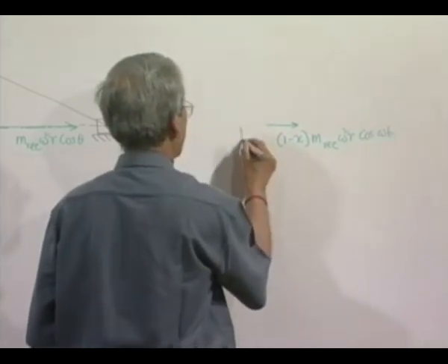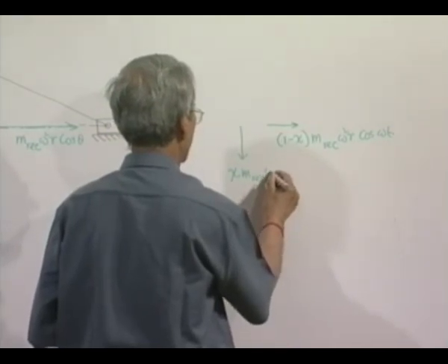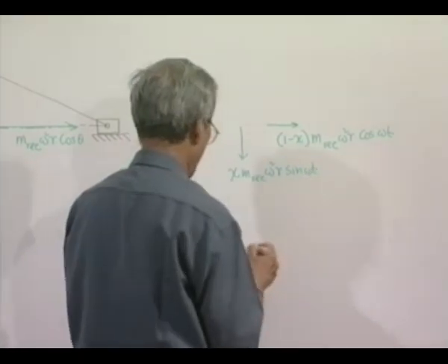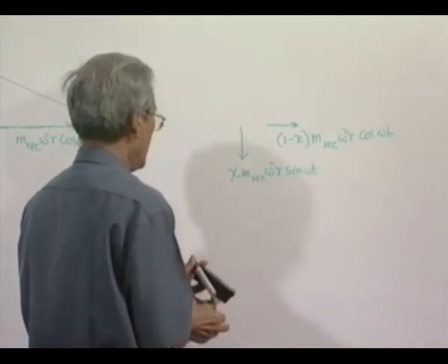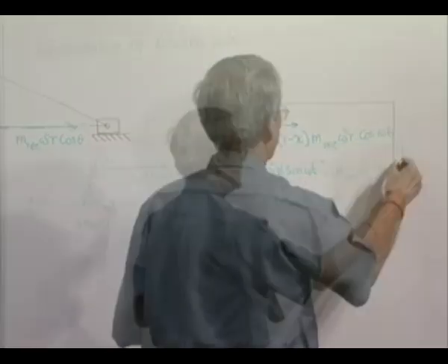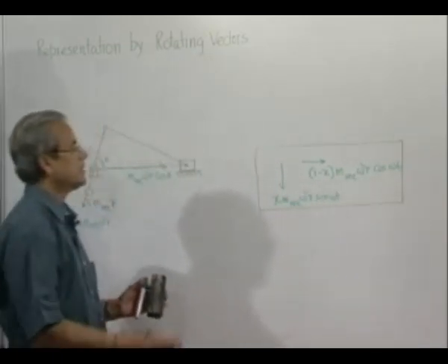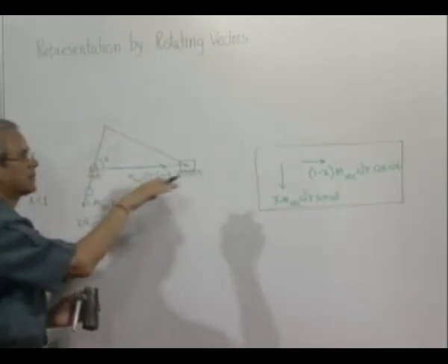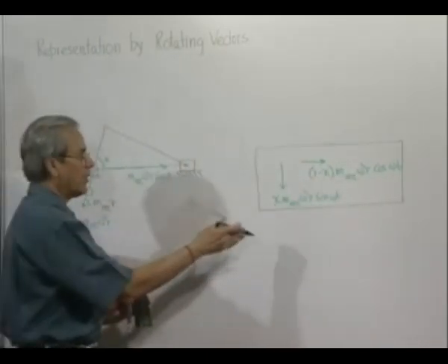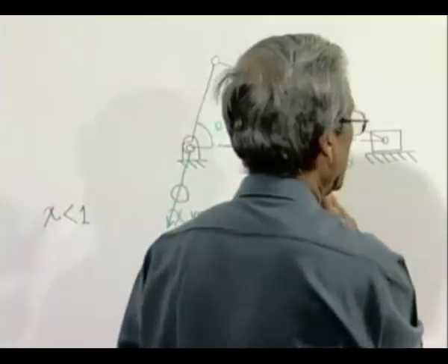and in this direction. So the engine, if we represent it by this outline, the unbalanced force in the engine in the x direction is this much, which is obviously less than this, but we have also produced another unbalanced force in the y direction, which is also less than this in magnitude.